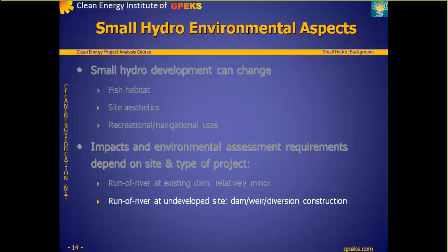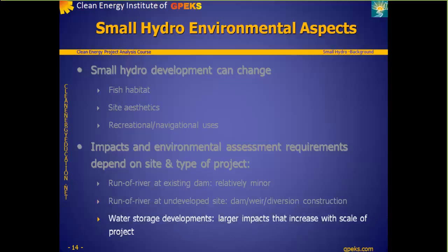While flooding is avoided, in projects meant to operate primarily during the times of peak electrical load, the water level upstream of the dam and the flow through the tail race and downstream of the project may fluctuate. In a large storage reservoir, this fluctuation is usually slow and not a problem. Downstream of the turbine, these fluctuations may be rapid and more objectionable.